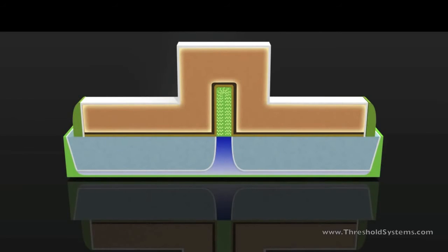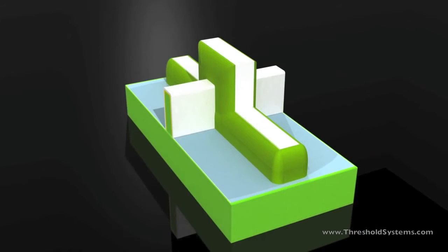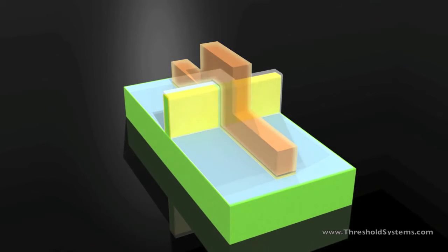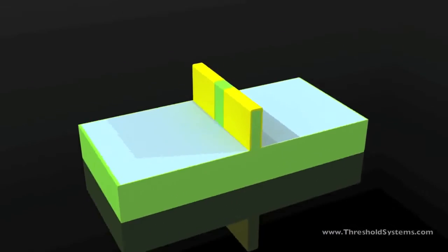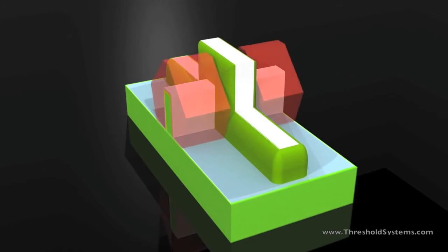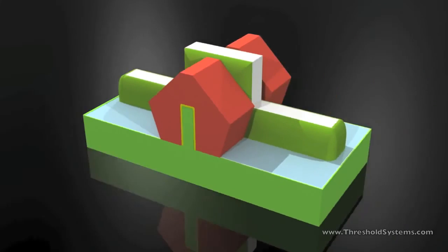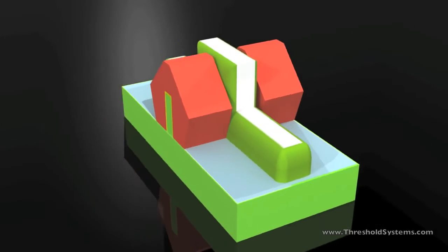Now, when the transistor is in the on state, the gate has excellent control over the channel because it is much more exposed. We can control this exposition using more parameters than in classical MOS. As in classical MOS, when the gate electrode is energized, it forms a pathway between the drain and the source for which the current can flow. To enhance performance, silicon germanium or silicon carbon stressors are laid over the source and the drain, as it is also done in common CMOS transistors.